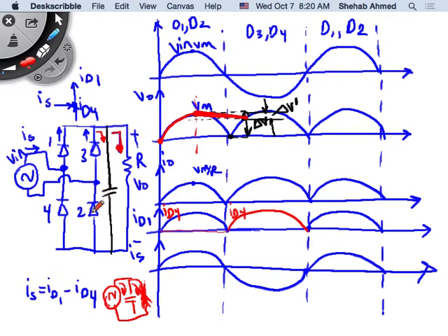I mean, this is source. Remember the RL source circuits? If I had increased the source, what would have happened? We started conducting only after the AC source was greater than the DC source, right? So it's the same thing here. Here now the DC source, which is the capacitor that I've charged, is higher than the input source. So the diodes will stop conducting. Diode 1 and 2 will stop conducting. So they will not conduct. So they will conduct all the way from here until the maximum.